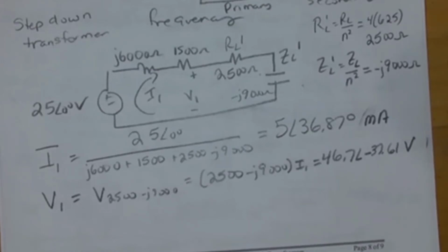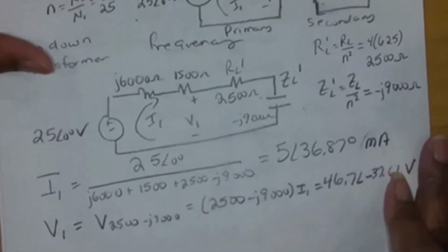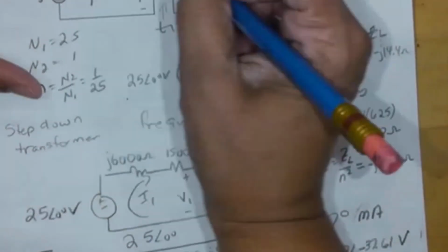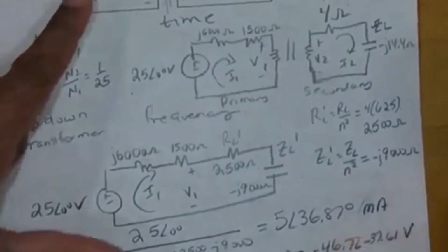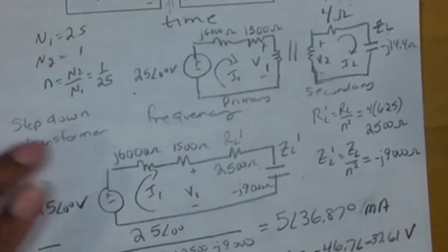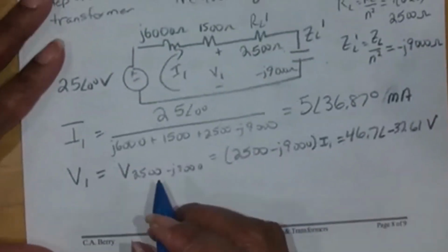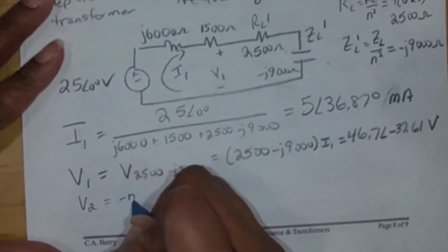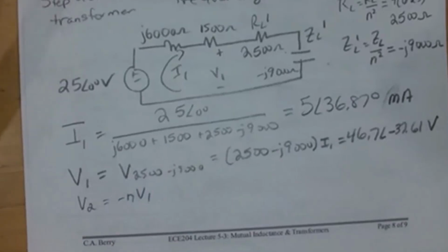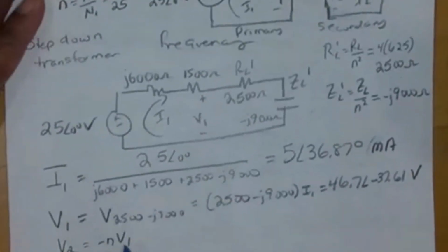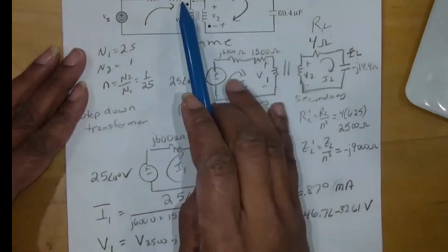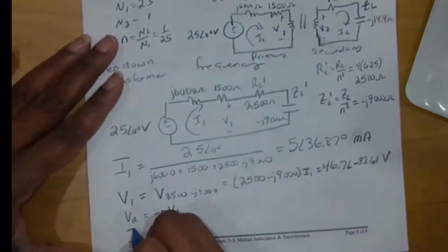Okay. So the last two values we need are V2 and I2. The way you do that is, because I1 and I2 enter at the dots on those two transformer sides, the formulas are V2 is negative N V1. Remember, the signs are dictated by whether it enters or exits the dot. So one's positive and one's negative, so that's why you use the minus sign on that. And then for the current, because they both enter, that's why I use the negative on this.